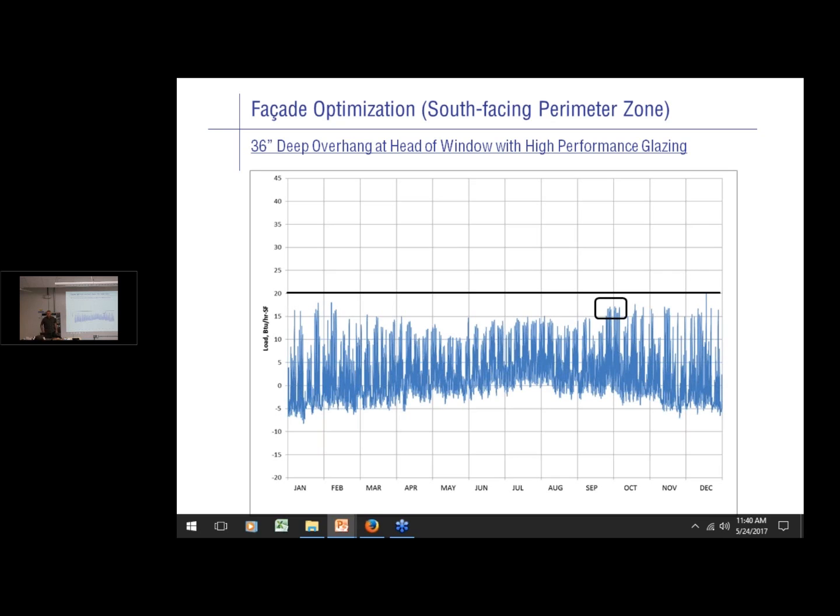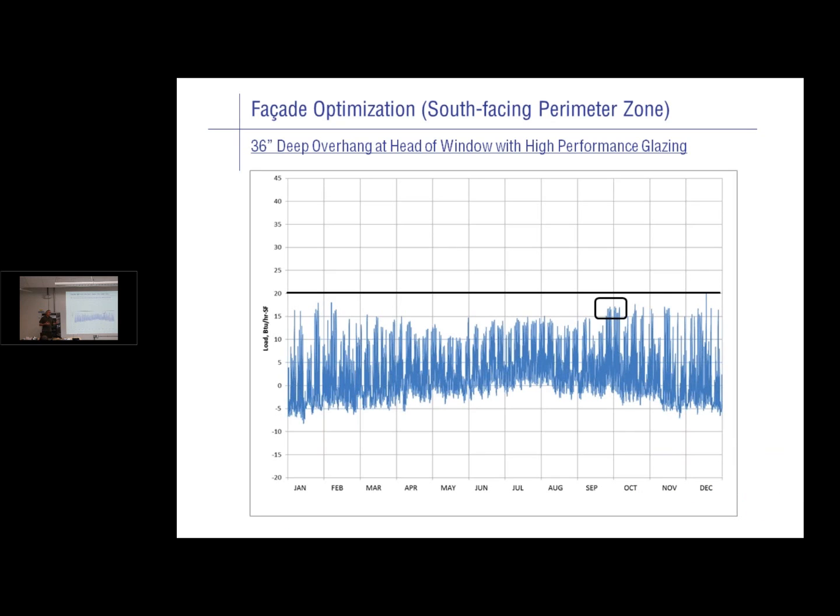Yeah. At this point, how much work have you done to really evaluate the internal loads of the building? Not much. I'm focusing on a study zone at this point, so I'm trying to get those internal loads reasonable for that study zone. I don't want them to be unreasonable. I want the schedules to be reasonable for the anticipated use. And I want the facade on that zone to reflect what the architect's early thinking is. But I'm not worried about the rest of the model, so I can just do a simple shoebox model with a little focus on one zone and just drill into that zone and study it.